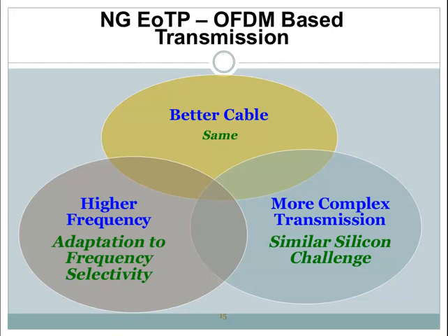Yes, but if we still use the single carrier, the challenge for single carrier modulation is that we need a really high-speed serial processor. Now for OFDM, we have parallel processing but a low symbol rate. What we need is powerful processing for the low symbol rate parallel processing. So they are essentially the same challenge.